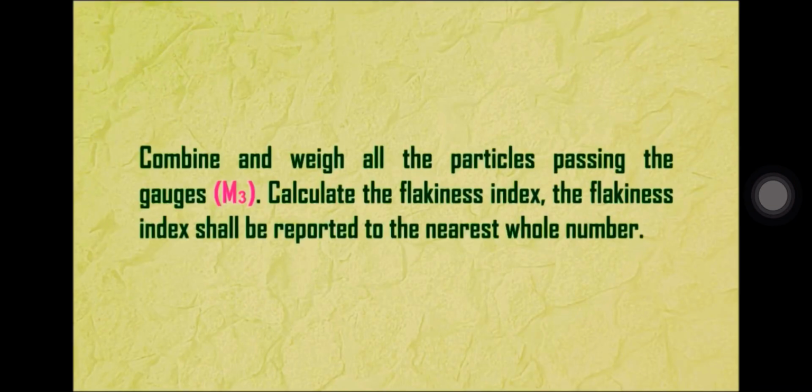Combine and weigh all the particles passing the gauge, M3. Calculate the flakiness index. The flakiness index shall be reported to the nearest whole number.